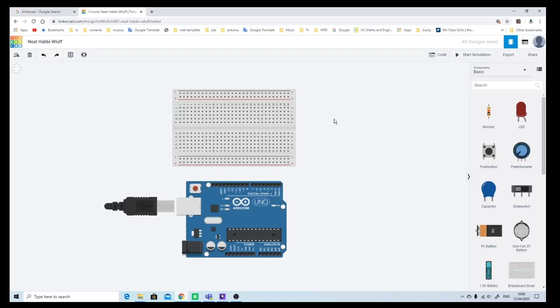Okay guys, let's show an example of the serial circuit. So obviously you need your plus and your minus. I'm going to show you how to make a serial circuit. You have your plus and minus. Bring the power to the breadboard. Then you bring in your LEDs. This time we're going to be using two LEDs, which is not hard.